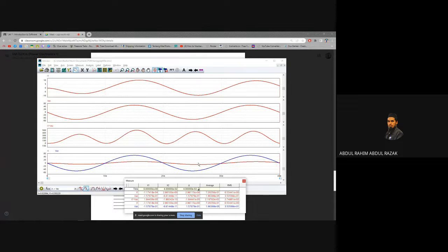Your circuit, is it a circuit that absorbs or uses power, or is it just like a capacitor or inductor only, which is not a real load, just storage. If you run a capacitor load or inductive load only, it does not consume any power, it is just storage. It will absorb power, release power, absorb power, release power. Average power is 0. So if the average power is 0, it means it is storage. If the average power still has values, then it consumes power.